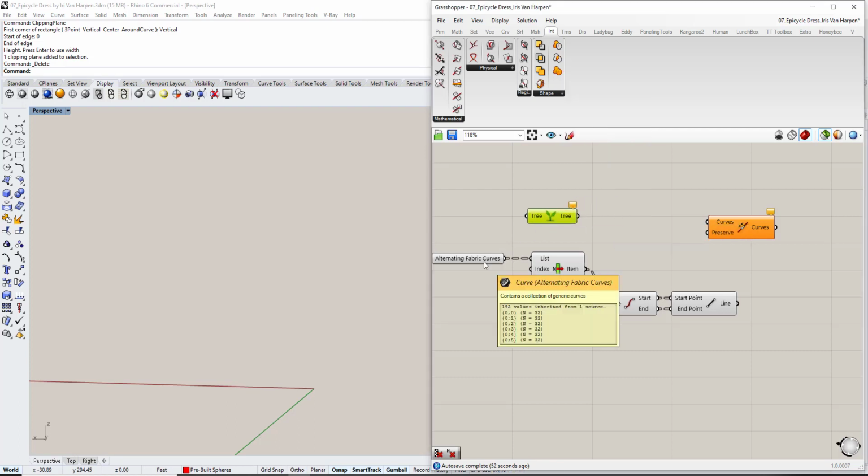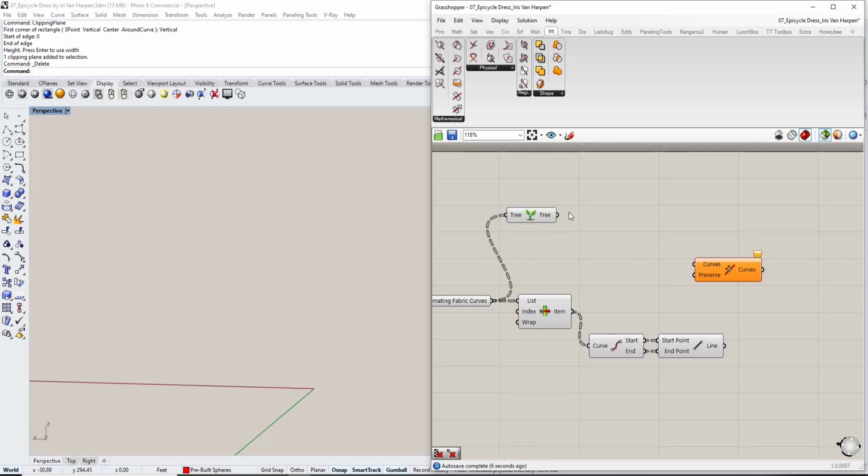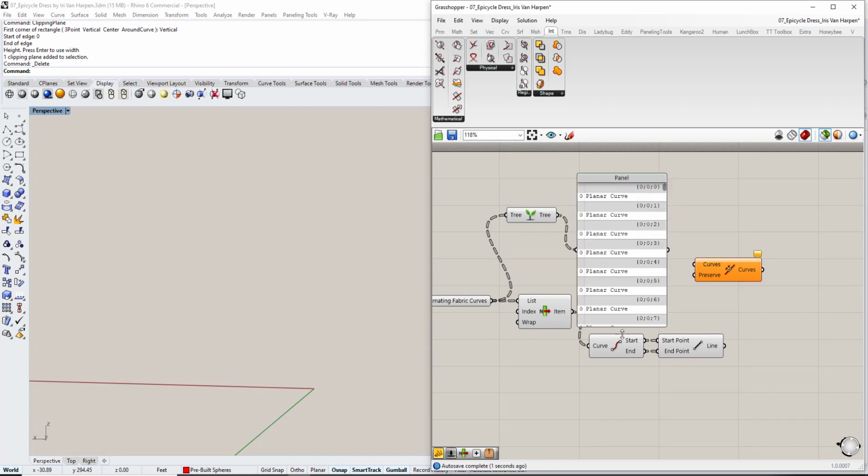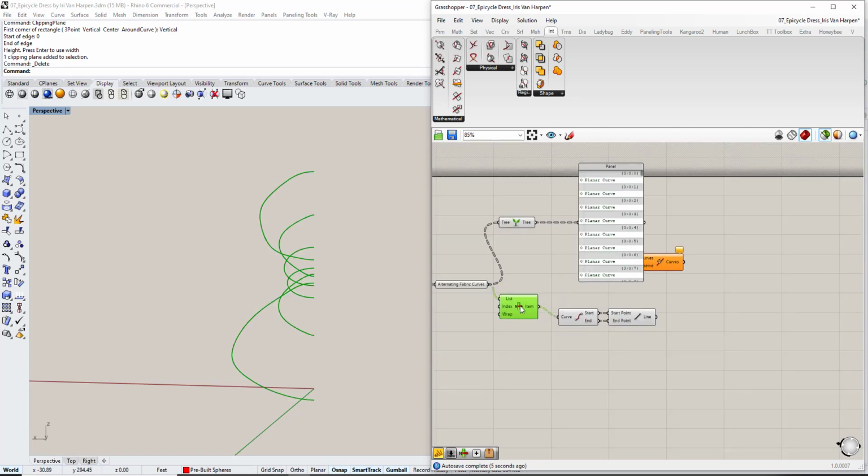What you need to do is if you graft this, right? So here you see how you have 6 lists with 32 items each. If I grafted it, each of those 32 items is going to be its own list, which is great. Look at that, right? So each of these are just singles now, 1 item per list. And if you want to see that, you can open up a panel, and you can see in the panel that each list only has 1 item. Okay, now I'm going to delete this list item. I don't need this anymore.